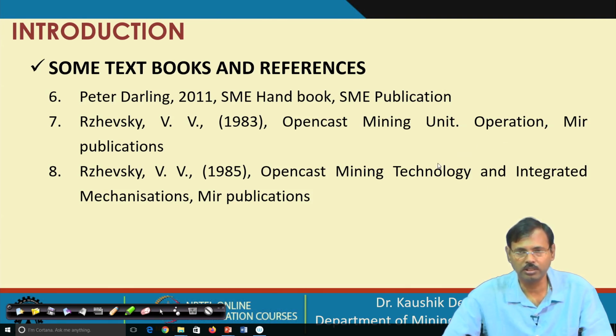It is very important for an engineer who is assigned the slope stability analysis job to understand the geological discontinuities very well. That is very important, because slope stability largely depends on the geological discontinuities, their orientations, their dip angles, their dip directions. So, significant knowledge in that area should be there for a slope stability engineer.